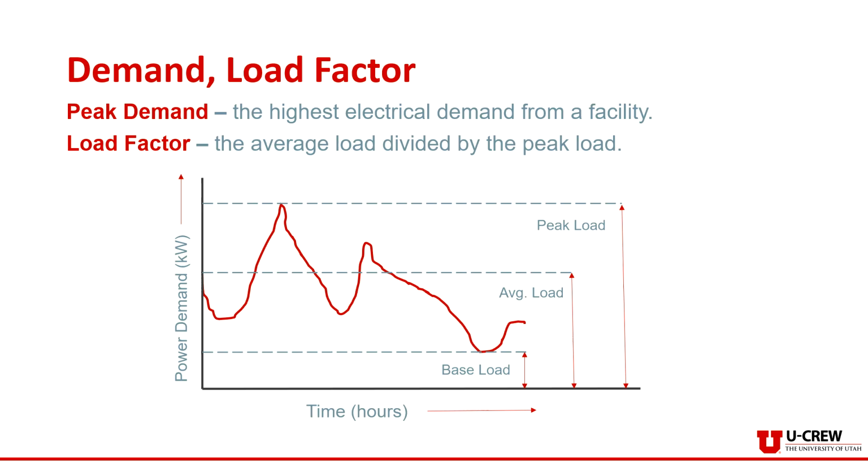That brings us to the second item on this slide, which is the load factor, and that describes how equivalently you're using power throughout the day. Similarly to power factor, ideally you'd want to have a high load factor, and you'd want to have a low power demand. This facility could decrease their bills by using less power during that peak and using a little bit more at other times of the day. This might be a little confusing now, but don't worry. This is something you'll get super comfortable with as you move forward in your work here.